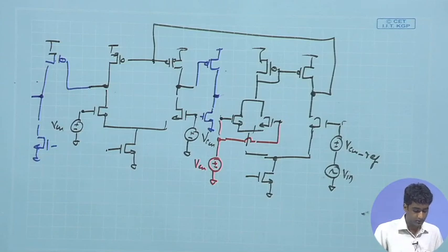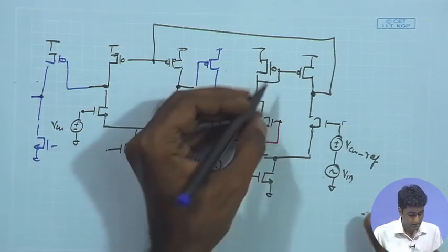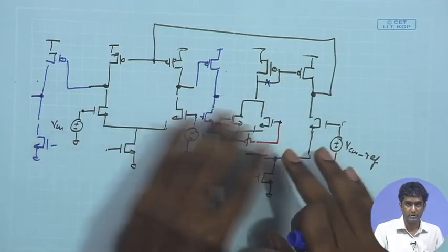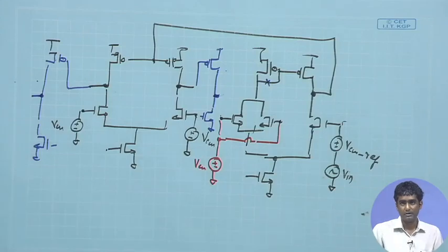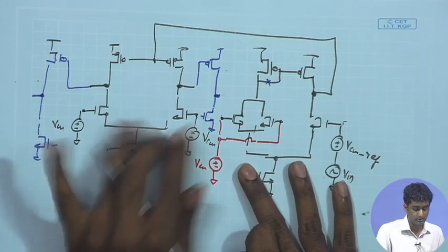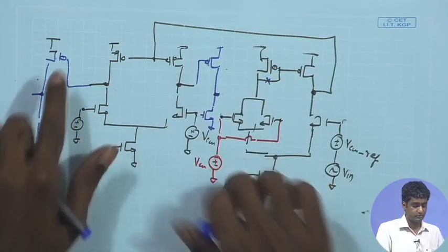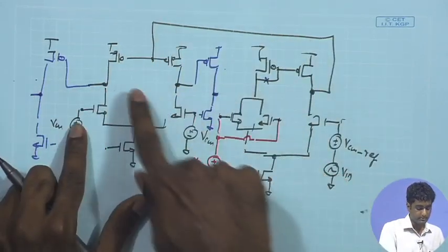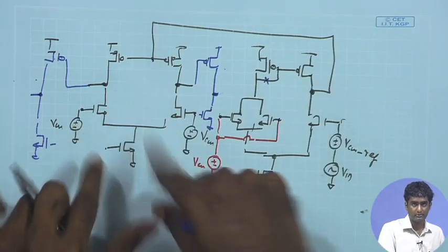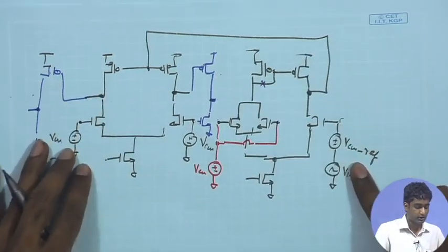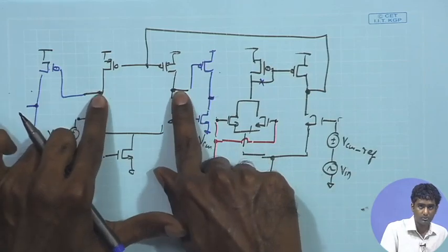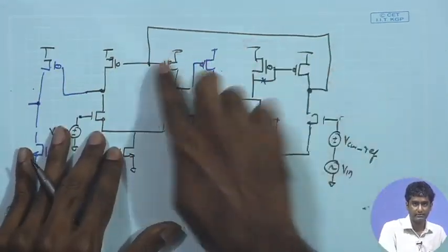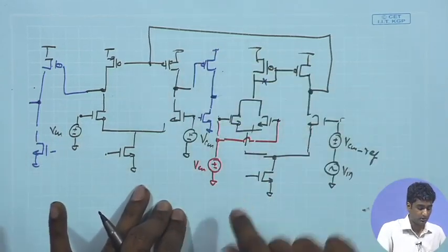The other thing that you also need to make sure is that you are checking the polarity of this one. Some of you have pointed out that when you connected the two stages in the loop, this particular scheme was not working, and that is because you have probably not changed the polarity, because for the single stage, this is the correct polarity because it is giving us overall negative feedback. You can trace it back and check whenever you have doubt. Assume that you are just having a single stage, and you are just trying to trace and figure out that yes, this connectivity was correct. To do that, what did we do?